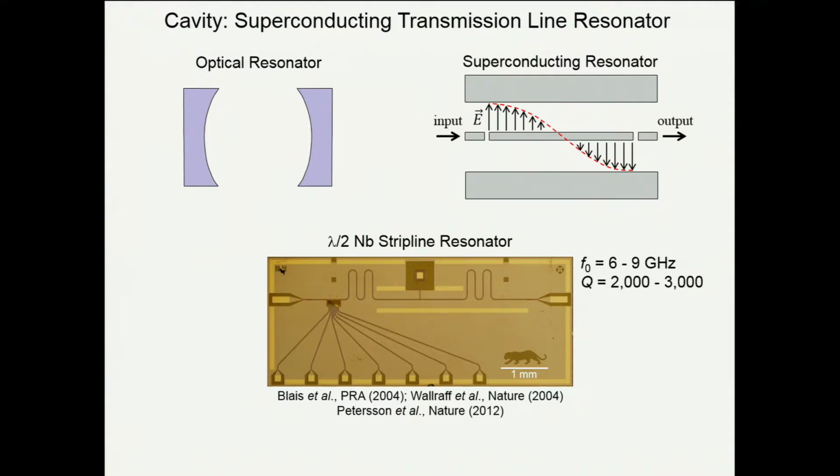It's way too high of energy to have any coupling to a device. So instead of coupling to optical photons, in our experiments, we couple to microwave frequency photons. And the way that we do this is by making a superconducting resonator. Imagine you take a coax cable, and you get out an X-Acto knife and slice through it. There's a central conductor in a coax cable, and then there's a sheath around it, right? So kind of lay that flat. Here's the central conductor. Here's your ground, and there's ground above it.